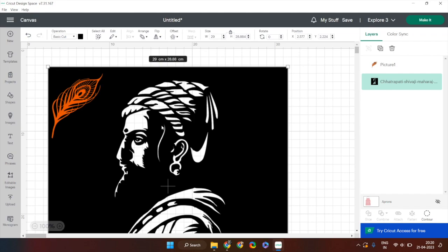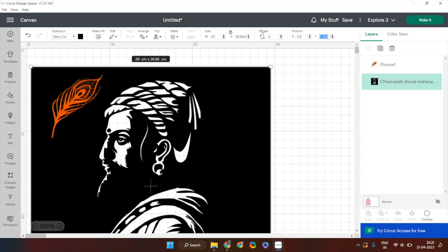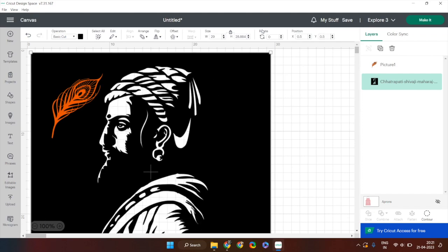But by default, if you want to preserve your paper and utilize the space as much as you can, always start with 0.5. Please do not start with 0. It doesn't give very effective results at the end. Sometimes some misalignment also happens. So after trial and error, I have come to realize that the minimum you have to specify is 0.5. You can still keep your paper at 0,0 so that there is some border, and the cutting starts from 0.5 centimeter to 0.5 centimeter.